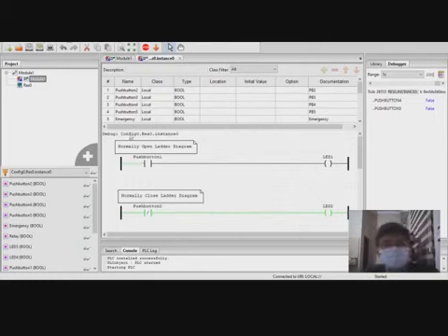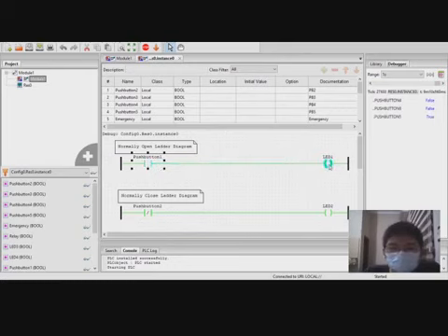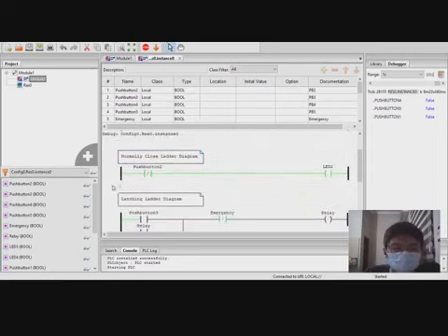And then we try to simulate this PLC ladder diagram. When we give a true value or we press the push button, the LED coil will turn on. And when we give a false value, the LED will turn off. And then in the second line, we have a normally closed contact. So the initial condition of this contact is closed.